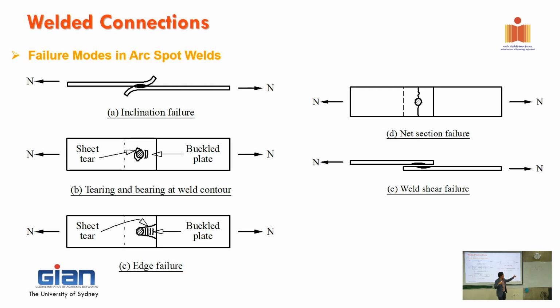But the nature of the thin wall in that area is very thin. Sometimes you remember it's 0.45, 0.42, the thinnest one, or generally 0.75. So it might buckle locally. That's what we call buckle plate. It might happen, and that's what happened in here.